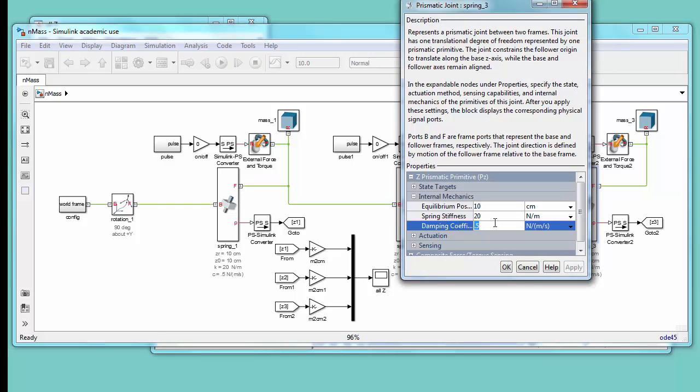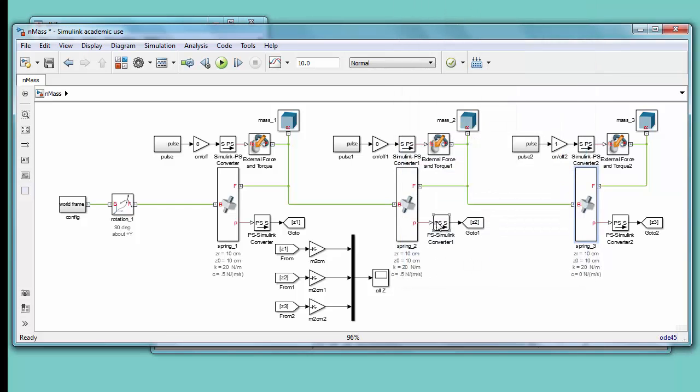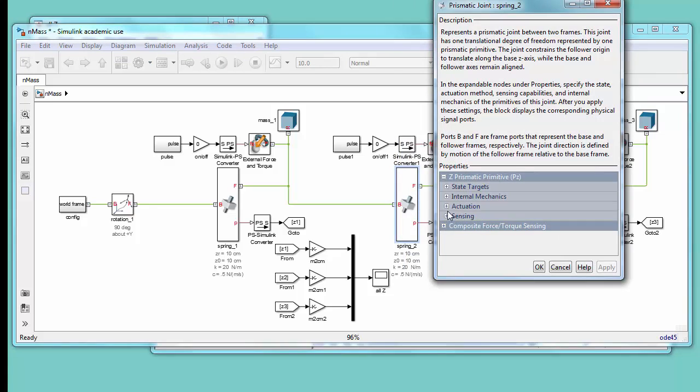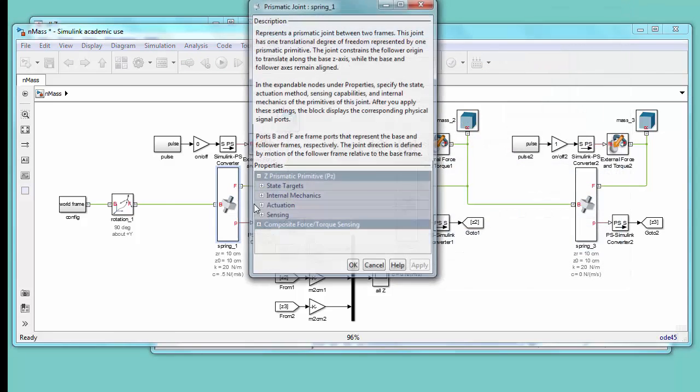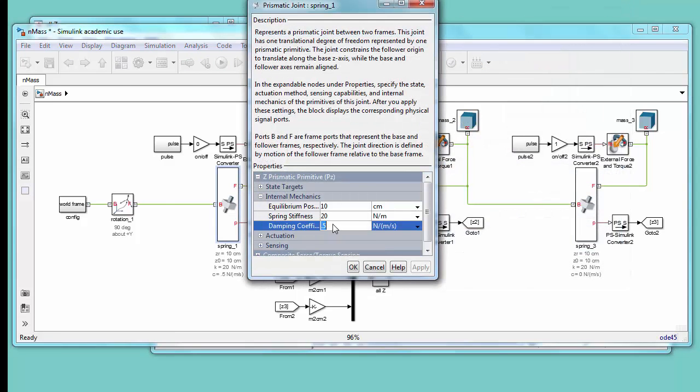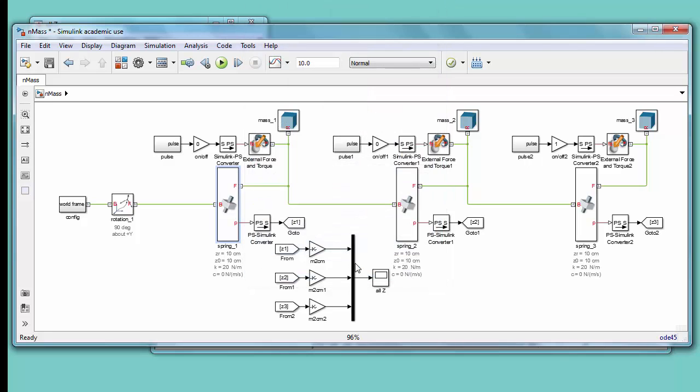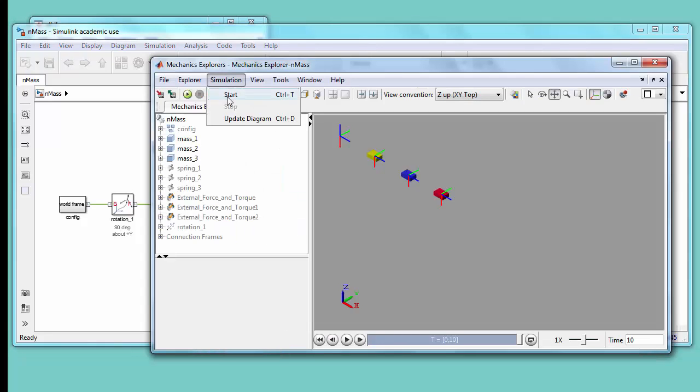What we'll do first is let's get this thing rattling around a bit. So I'm just going to get rid of the damping on all three spring mass damper systems. I'm just setting the damping coefficient to 0 in all of these. That'll make for a little bit more interesting response. Update and then run. And now you can see things wiggling around relative to each other.